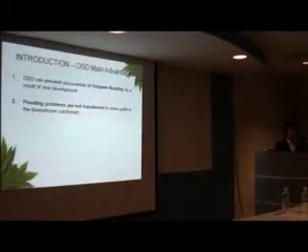This small rainstorm is referred to as frequent flooding. Another advantage is flooding problems are not transferred to some point in the downstream catchment. The intention of the OSD is to give zero impact from new development, not to solve existing flooding problems.